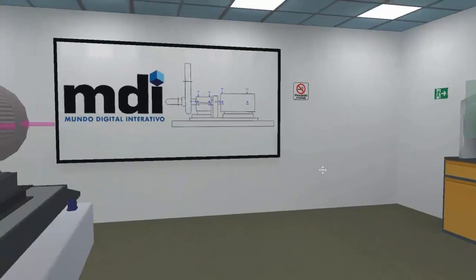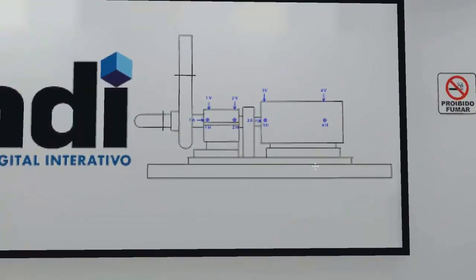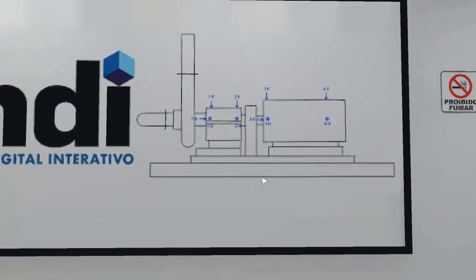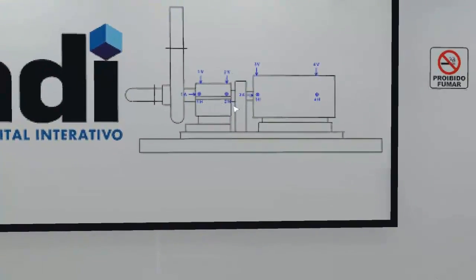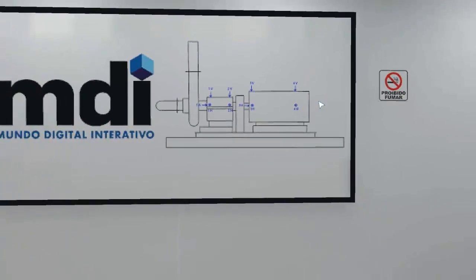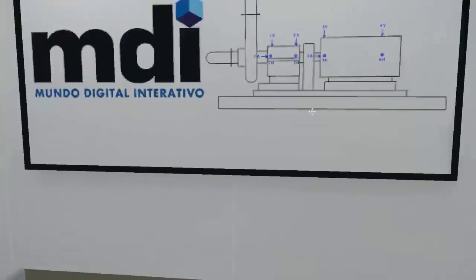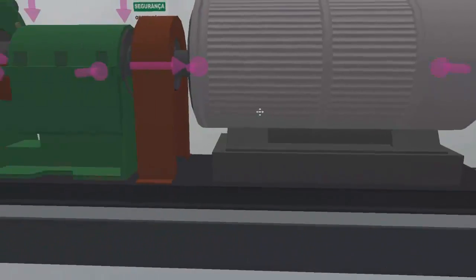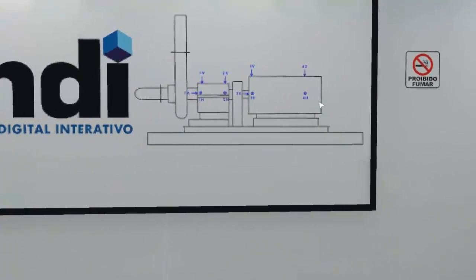Let's look at the picture on the wall with the references of the measuring points. Note that you will do the measurements in 4 sections. They are located on each of the bearings, both the pump and the engine. The directions measured at each point will be horizontal, vertical, and axial, except for the points in sections 2 and 4, where the axial component will not be measured, for reasons that will become clear during the vibration measurement chain class.